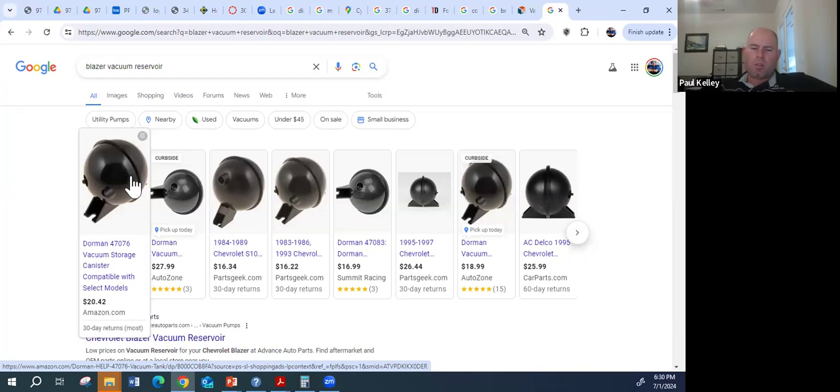I ended up talking with my mentor, which is like the last resort. And he's like, oh, check the vacuum reservoir. I'm like, what? It's got an intermittent AC concern. And then I thought about it. Oh yeah, it's vacuum controlled. This thing had a crack. So driving around, the engine made more than enough vacuum. But when I went wide open throttle, it should have been enough to store for a nice long hill, but this thing had a crack in it. So it was leaking vacuum, and air was rushing in.